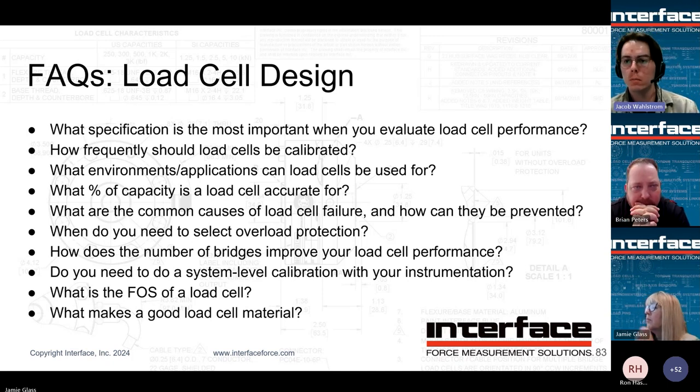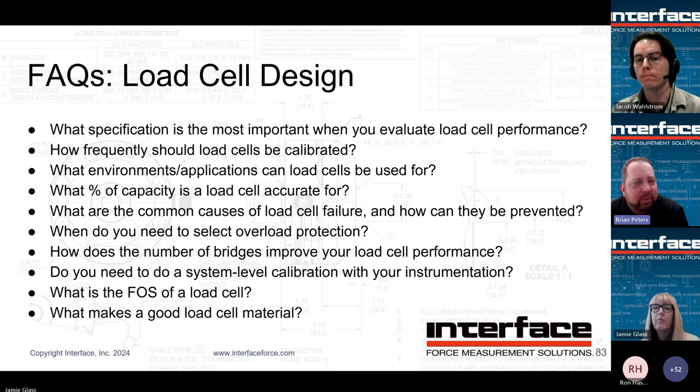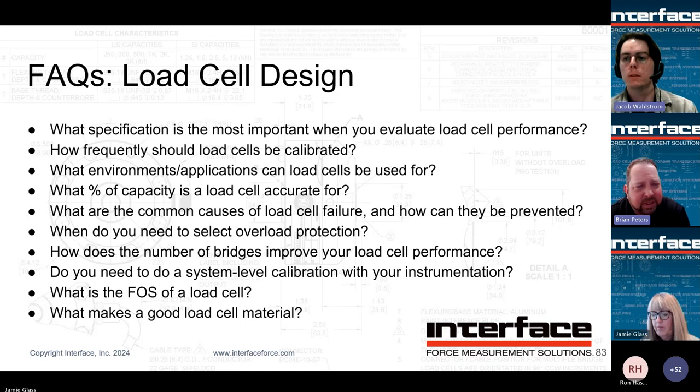Load cells are not really made to withstand shock loads, so it's really good to make sure that you're doing everything you can to avoid those. Or if they have side loads that aren't expected, right? Now all of a sudden the strain the bridge is seeing at full scale is a lot worse than maybe expected. So especially if it's high cycles, you've got to be extra careful there. Fatigue type testing. Absolutely.